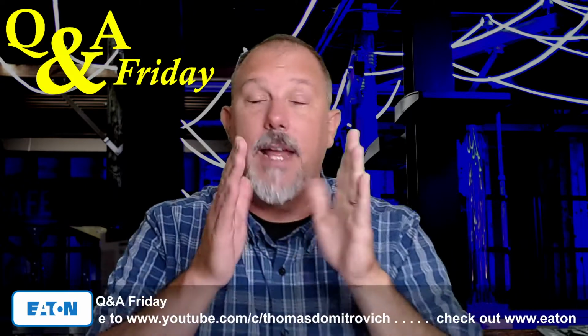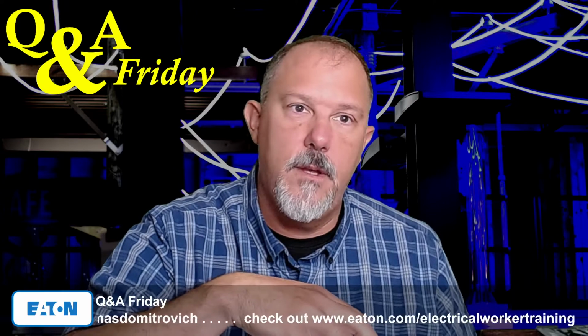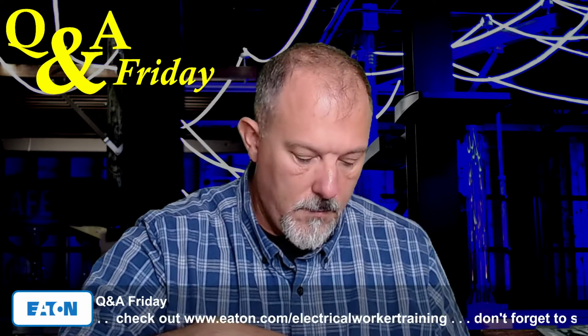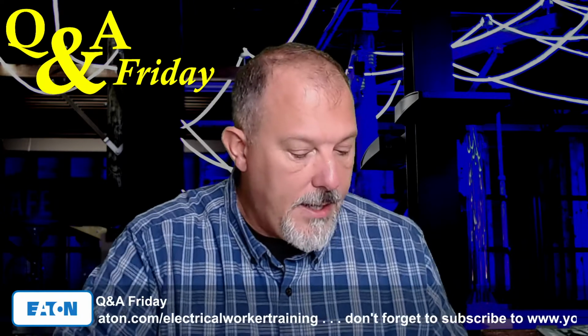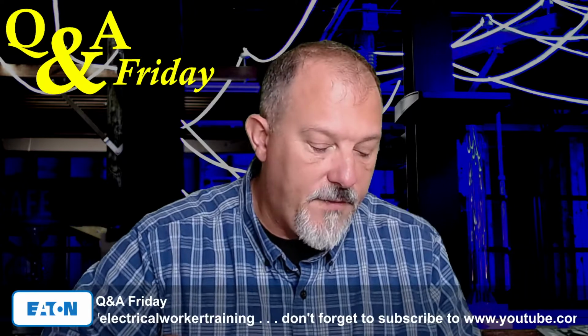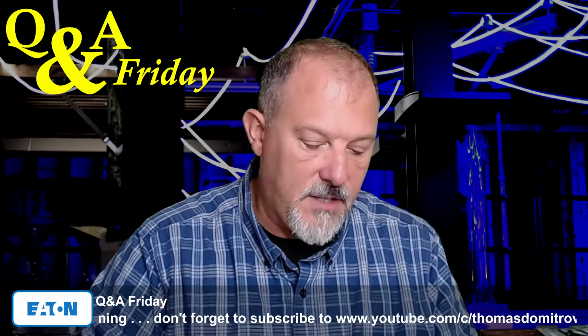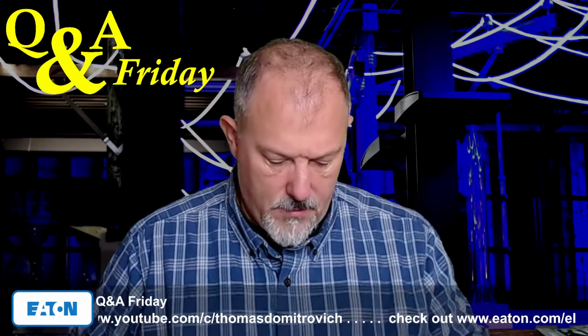All right, let's just answer that one first. Remember that GFCI protection, when we say in 210.8A, we say all 125 volt through 250 volt receptacles installed in locations specified, right? And anywhere where we talk about... A was not a good example. Let's pick another one.